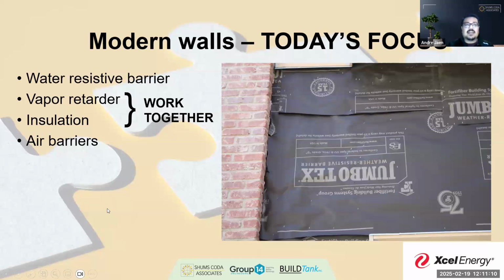We want to make sure that it's clear to everybody that these are the ones that are really trying to work together within that wall cavity to make it clear where that moisture can go, where that air is getting washed, and that's being limited down as much as possible. Whereas your water resistive barrier is a much older requirement that's been around a lot longer and really focuses on wicking that moisture away from the wall assembly, away from the foundation, telling it where to go.